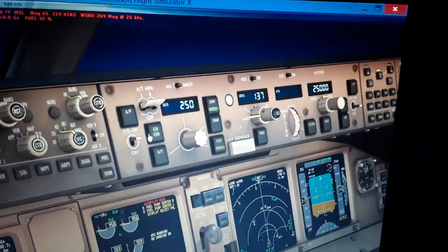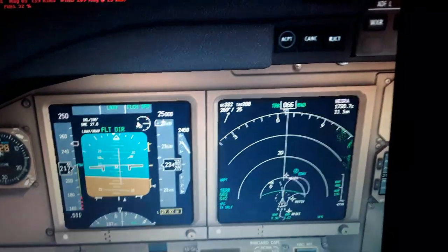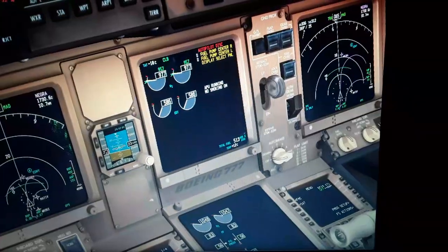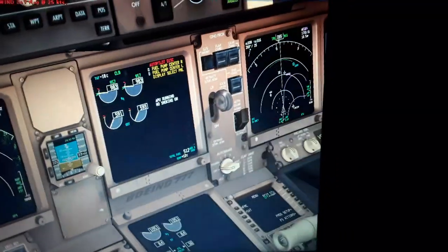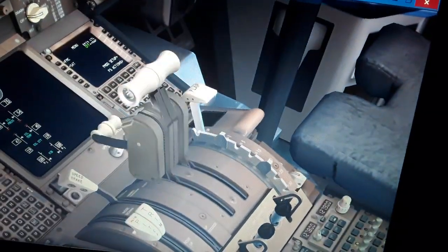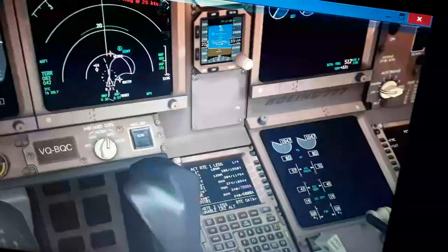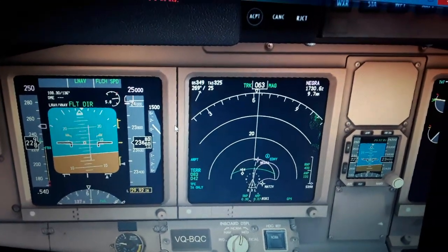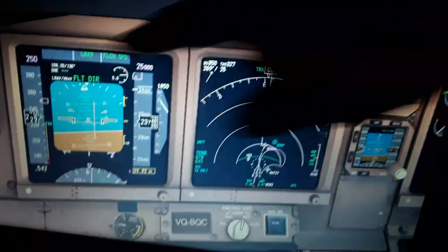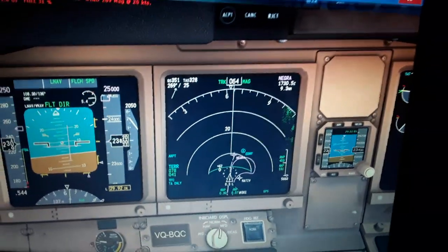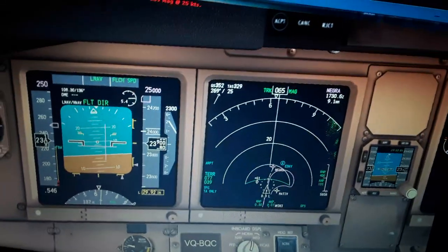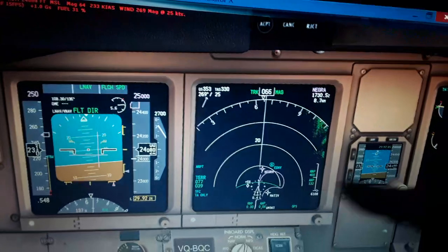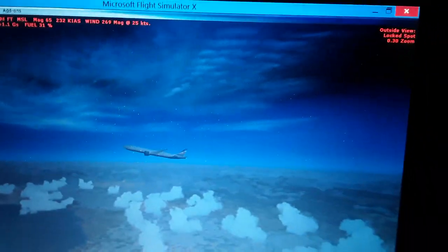So we turn off the auto thrust like that and use full thrust like that, just for climb out. You see the thrust here. We can apply manual thrust now to increase the rate of climb a little bit. You can see the flight director, the auto thrust symbol is off right now. You can see some margins here. So we crossed 34,000 feet now.